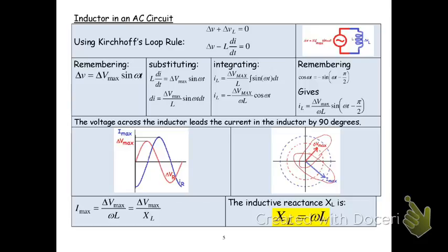I'm not going to justify it here, but I can then create a thing called reactance, which is like resistance. Mathematically, it does the same thing. I equals V over R. Oh, omega L is like my R. Let's call it XL. So there's going to be a new term called reactance, which is doing the same job as resistance. Same units, same everything. Don't know why they didn't call it inductive resistance, but they didn't. I guess because an inductor has a resistance, which is different.